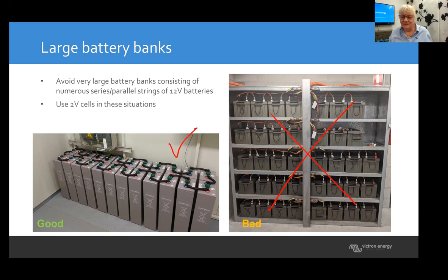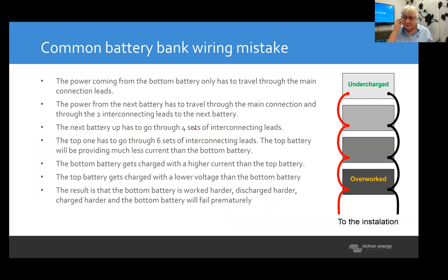You have the same volume, the same price probably also, because that's all not cheap. You all have to put them on top of each other. It's a crazy system there. This already looks way better. It's really nice to install, and if you need a battery bank that big, you need to go to 2-volt cells or lithium. That's another option. Or redox flow batteries or something like that. So you want to have batteries that are dedicated for that sort of stuff.